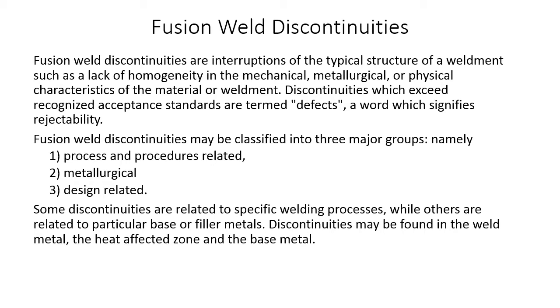Design related. Sometimes the designer just gets it wrong, and you're going to have to fight that design trying to produce a reasonable part. So sometimes design is just going to kill you. Some discontinuities, like I said, are related to specific welding processes, base metals or filler metals. Sometimes you get a bad batch of filler material.